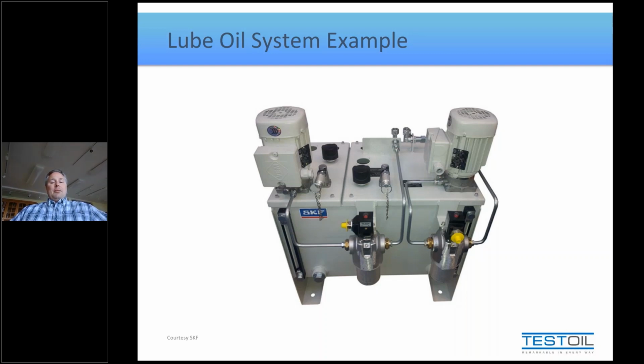If you look at it from a reliability or criticality standpoint, you might say those pumps are critical. Without the pumps, we're not circulating the lubricant. And without circulating the lubricant, well, the machine that we're trying to lubricate will trip, will fail. So our sample point location becomes, we should sample from the pump outlets. That would tell us if the pumps were about to fail.